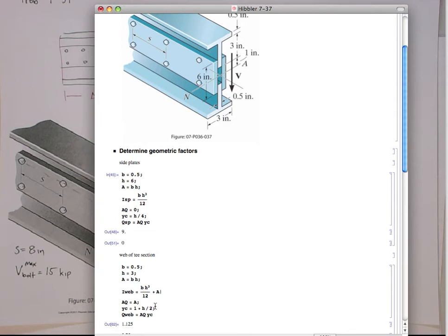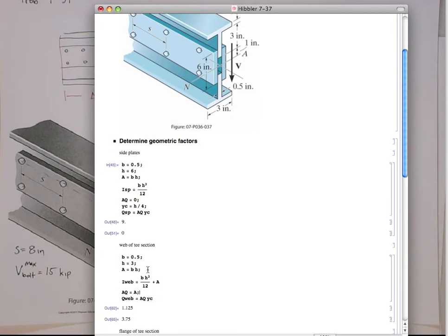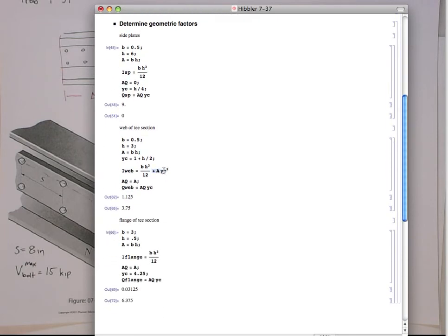So if I put this term up here, I can use that. This is going to be the YC squared. Right, so that does the parallel axis shift. We can do the same down here, because the flange also has to be shifted by parallel axis, but we have to make sure we get the right centroidal distance, okay?